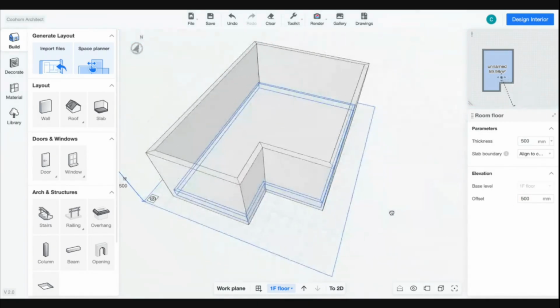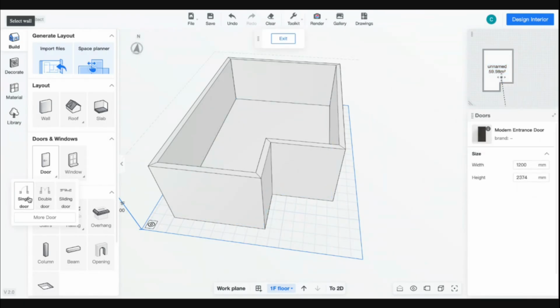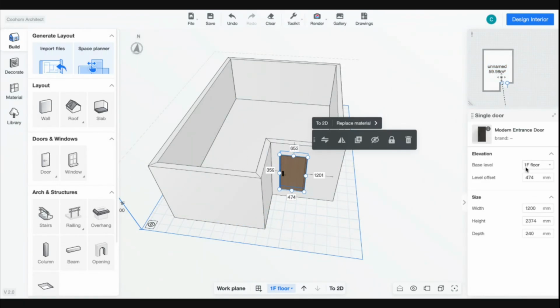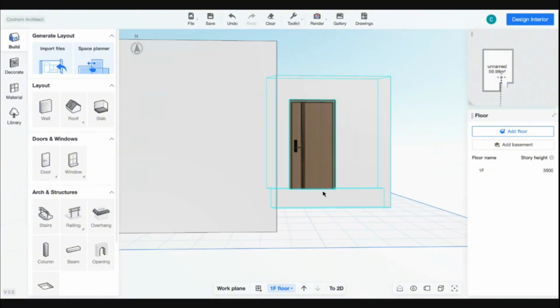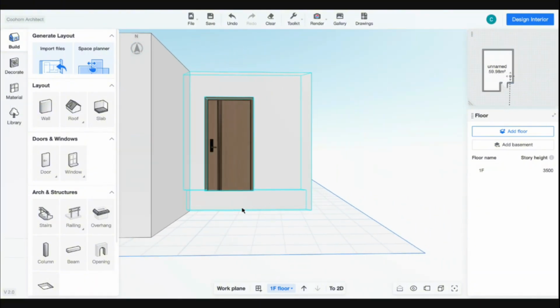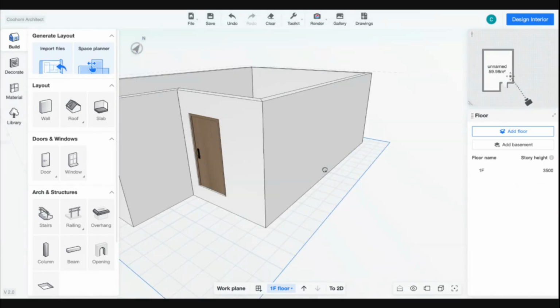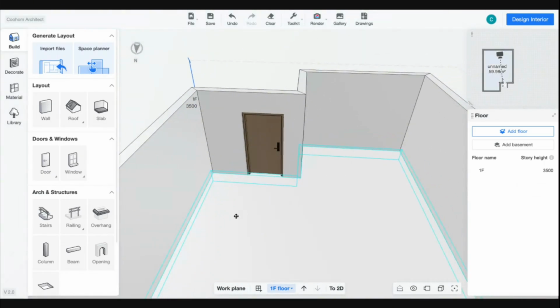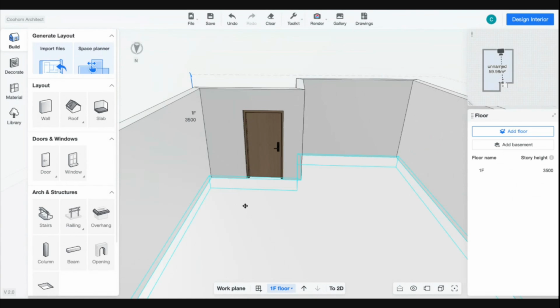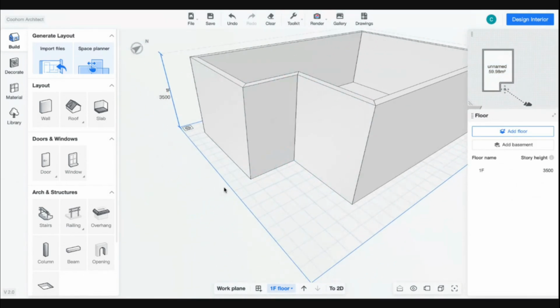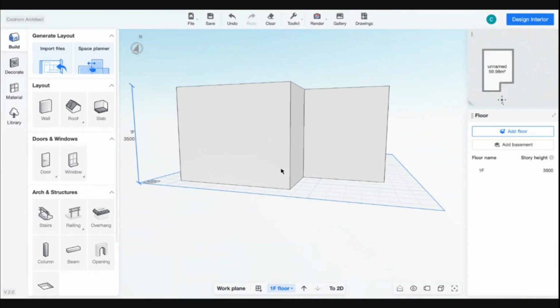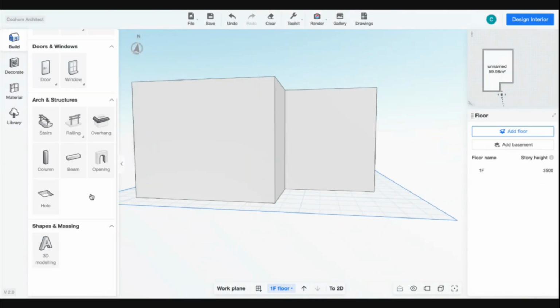Okay. So once you click the doors, you create a new door here. Just click new doors. You can see you can change the offset level of the doors also to 500. So if you see from the exterior, you will see there's a gap between the ground level and the doors, right? But if you go inside, it's actually the same height. I mean, this is the ground level of the building. Okay, so we're going to start the design from the custom model first.